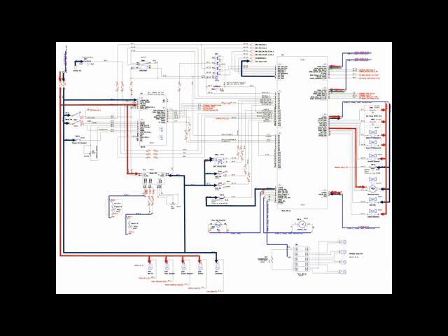At this point, all the outputs are only one leg of the needed power to all but two devices. The door switch is powered at all times, the relay board is powered, and the drain is always powered on either the open or closed leg outputs from J8, depending on the status of the D101 LED on the relay board.